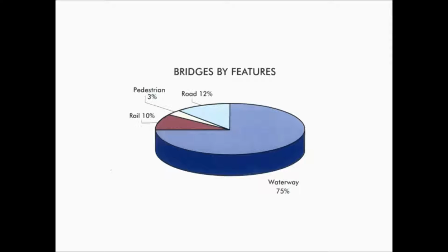And to analyse Australia as a whole would not be representative for your particular state, but taking the information I've just shown over the last 3 tiles, it breaks down to say that there's 4,990 bridges, 75% of them are over water, 56% of them are highways and freeways, and 17% being steel. And that steel structure, or those steel structures, would suffer from more issues by way of corrosion compared to concrete structures, and our focus should be on that 17% or on steel structures.